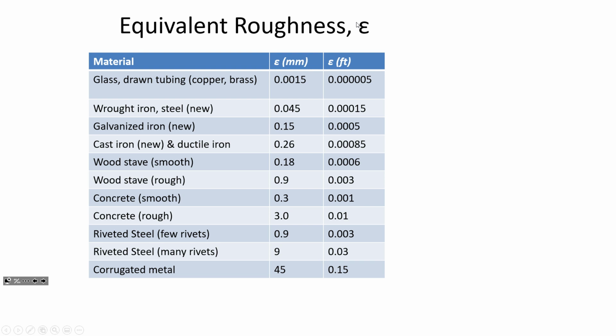In the pipe rack, you remember that bottom pipe that you didn't use in the experiment last semester? You just used the top 4 pipes. Those top 4 pipes were stainless steel, and the one on the bottom has sand glued to the outside of it. So if we measured the grain diameter of that sand, and we knew what the equivalent roughness was, we could use that as a measuring stick, so to speak, trying to relate other materials to how rough they are, to what is the equivalent sand grain diameter that would be glued to a surface.